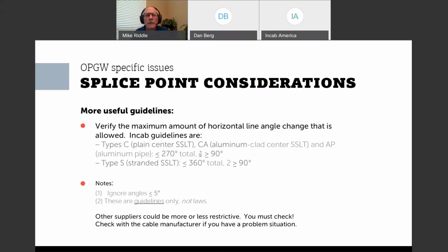Okay. Can you provide a list of machines and tools to execute the OPGW deployment? Yeah, but not during this webinar. Usually that's a function of your installation instructions, and what we could do is send you a copy of our installation instructions and then a general guideline for installing OPGW as well as other types of cables used by utilities is IEEE 524.